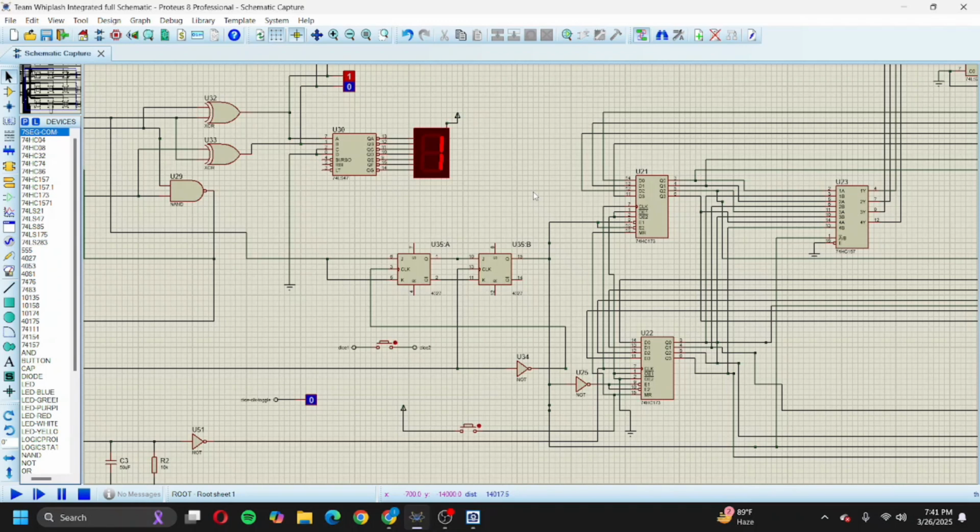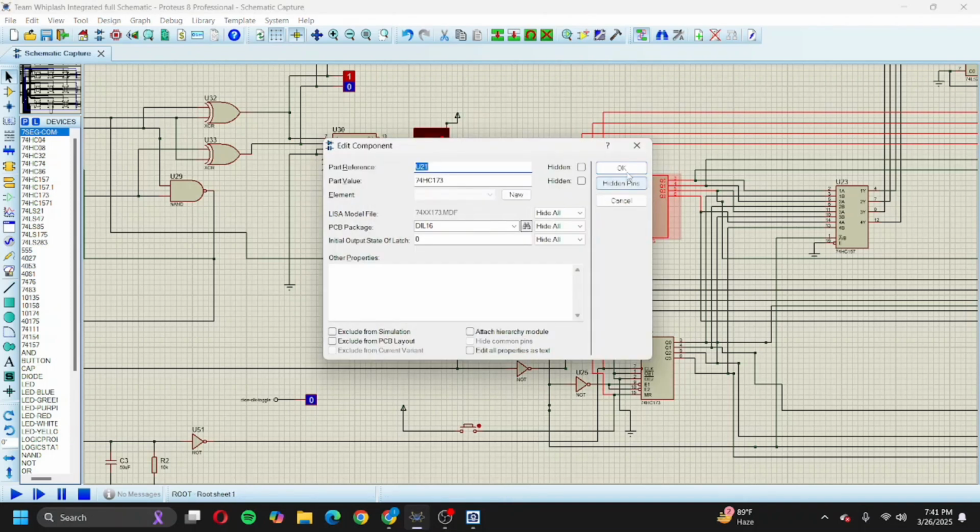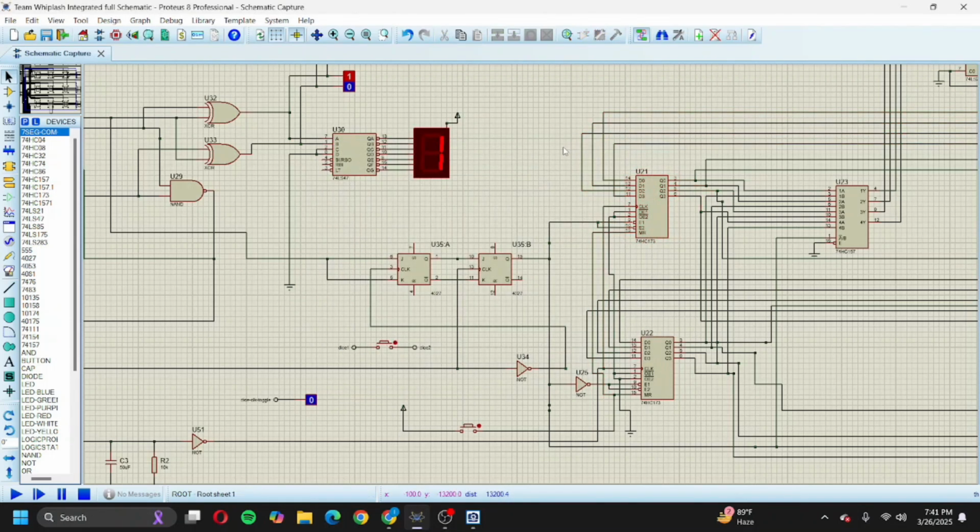Now in the memory module, the clock pulse of each register has to be triggered whenever the push button of the dice module is released, because if the clock pulse is triggered the moment the push button is pushed, then the register will take whatever instantaneous value is updated through the logic module, since when the dice button is pushed, the number is still being generated. So it is better triggered when the dice button is released.